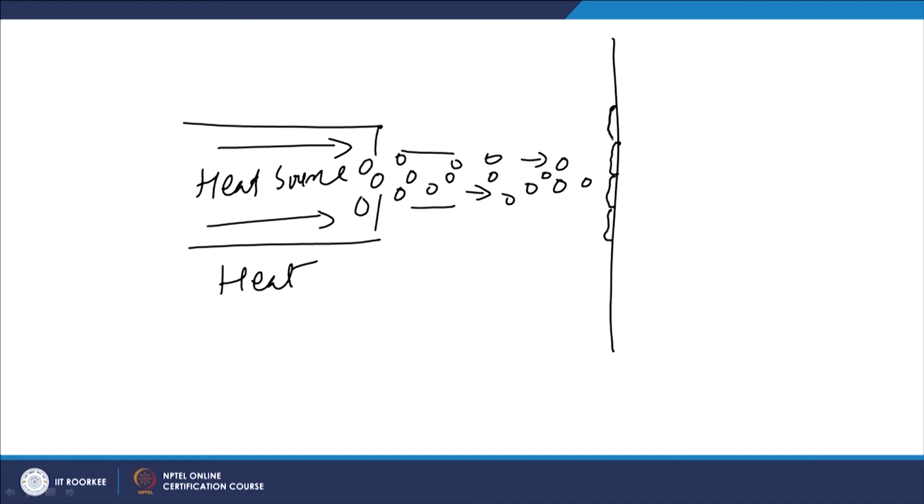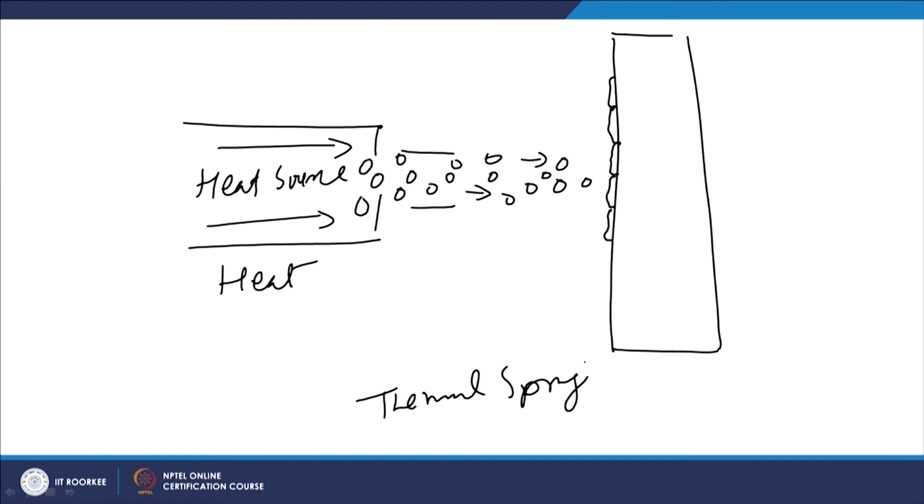So, this is how a layer of the material required to be applied on the substrate is developed in case of the thermal spray process. In thermal spray, if we are using gas combustion, then the amount of heat transferred to the substrate will be less as compared to the case when some kind of arc is used, because the cooling rate